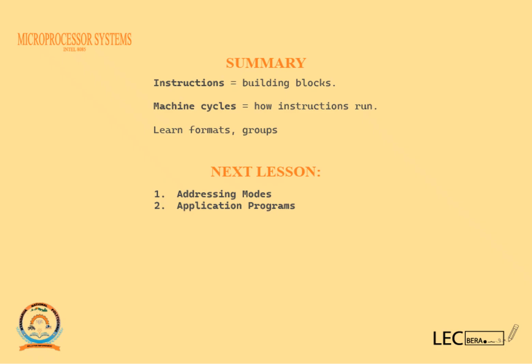In the first session we discussed how the instruction is built, and we see that programs are made of what? Instructions. Instructions are the building blocks of what? Programs. An instruction can either be 8-bit, which means it contains only an opcode, or 16-bit, which means it contains an opcode and an operand, or 24-bit, which means it contains an 8-bit opcode and a 16-bit operand.